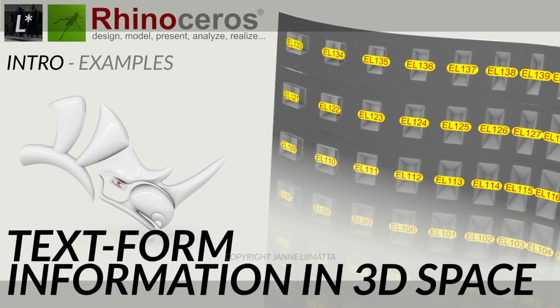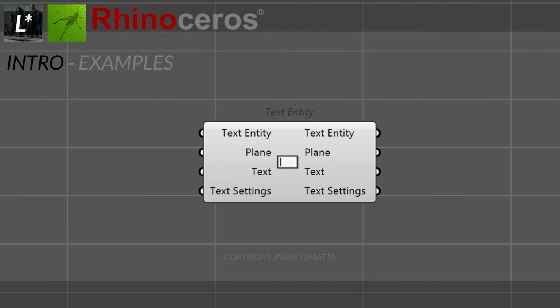We are going to make element IDs using the text entity component and display them in 3D for ease of access. The text entity is a new component in Rhino 8, again found in the Rhino tab of Grasshopper. It has 4 pass-through parameters: a text entity, a plane to display the text on, the text that you want to display, and text settings, which can be changed with the annotation text settings component.